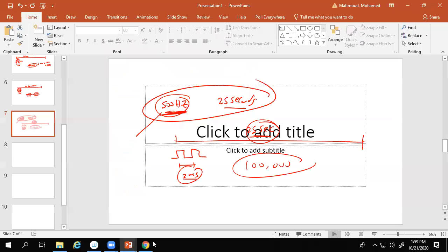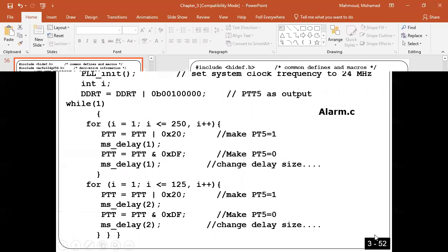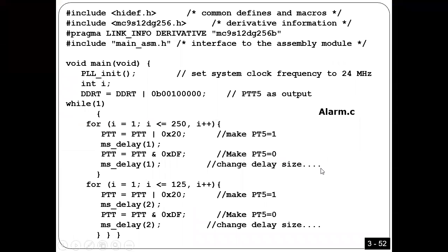Anyway, so what I'm gonna do now, I'm gonna explain the same program, but in C. So everything is almost the same, but I'm gonna use the format of the C language. Okay, so let's see how I made it. Look here, guys. Number one, you need to configure BT5 as output. That's number one. So this is how you configure it.